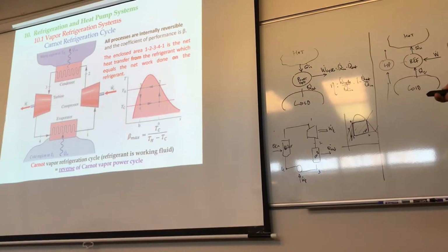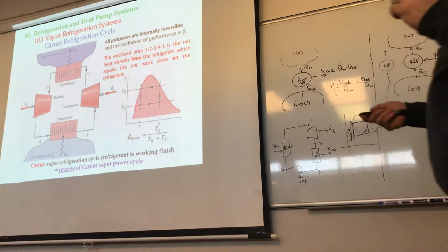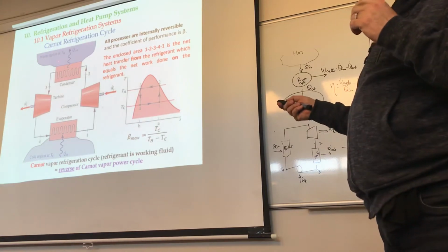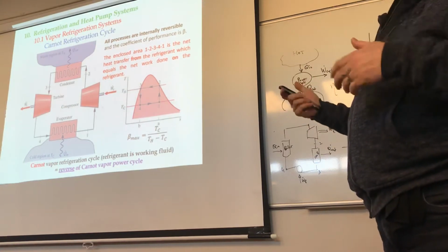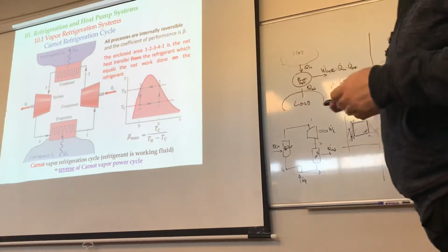And then you pass it through here at constant temperature through the evaporator. As it passes through, it sucks up some more heat from here. When it's low pressure, yes. So it sucks up the heat at low pressure and then rejects the heat at high pressure. That's really how it is. Because at high pressure, that's where you get hot, right? And then you reject it back.